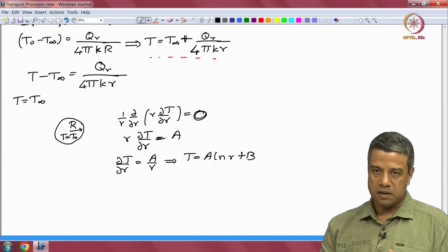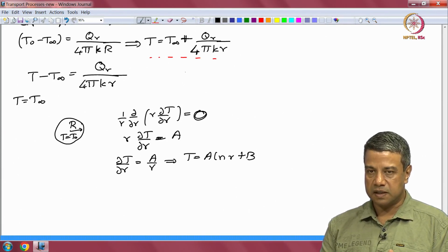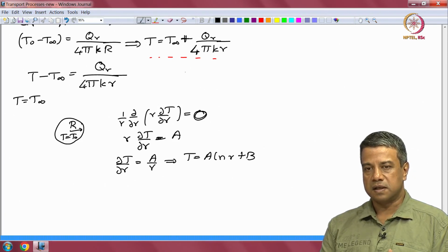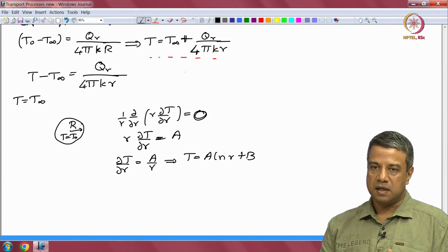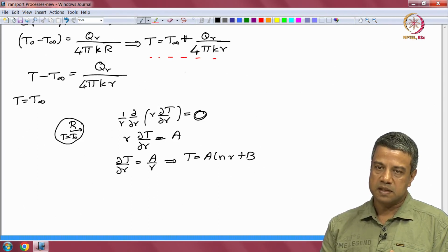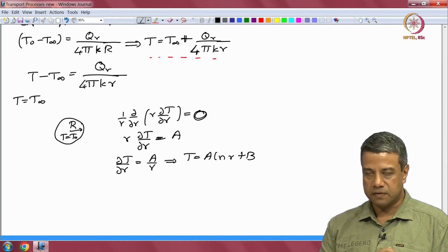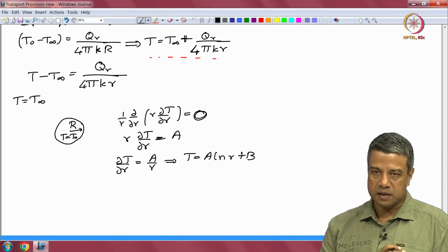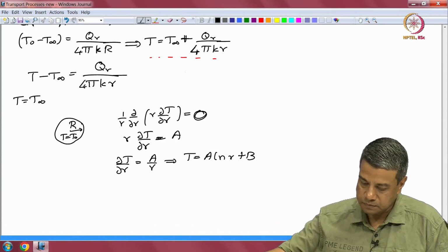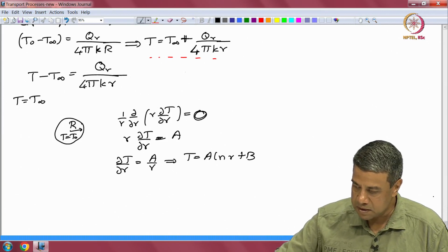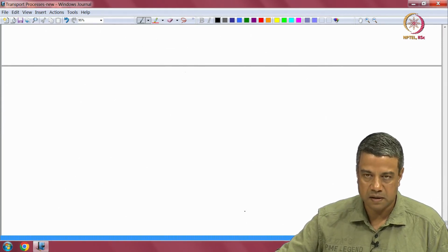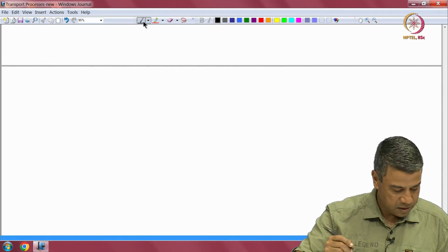Okay. So, even though we may idealize it as a cylinder of infinite length in an infinite medium, that does not have a solution. You have to consider the conduction from a cylinder of finite length, and the extent to which conduction takes place is comparable to the length of the cylinder, for this reason. Whereas for a sphere, conduction from a sphere into an infinite medium in 3 dimensions does have a solution. And that was the reason when we discussed conduction from a cylinder, we had actually taken 2 radii, the inner and outer radius.